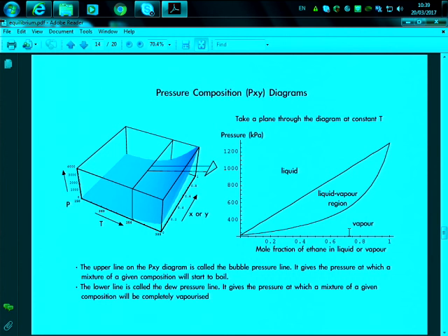Okay, so normally, for example, in compressors, what we want to avoid is basically having a multi-phase flow. If we have a compressor, we want to stay in the vapor region, and we don't want to go at all into the liquid region because that will affect the compressor if we start producing liquids in the system. So you have to ensure that the system is designed to not hit the liquid vapor region or change of phase in the system.